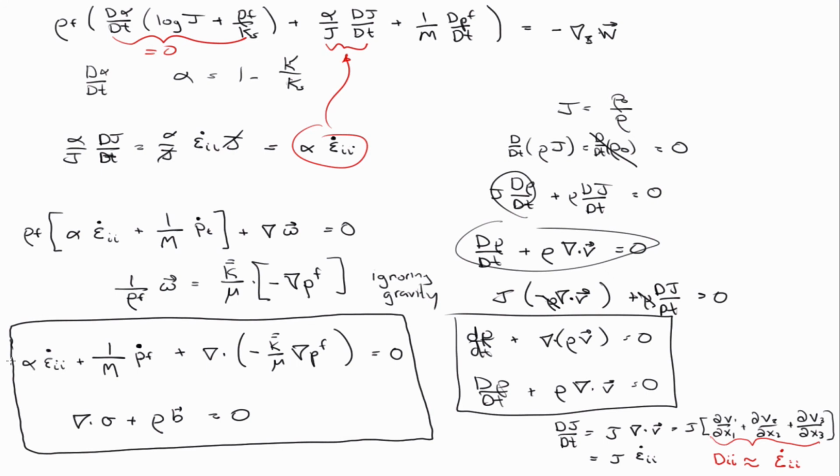In this case, the only time dependence is in the diffusion. So we're going to ignore inertia in the solid, which is typical certainly in a petroleum engineering geomechanics setting. If you're doing earthquake engineering or faults or landslide type stuff, then you certainly want to include inertia. But these are the equations we're going to solve.